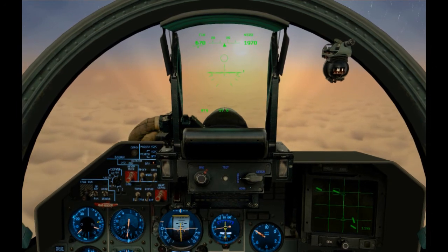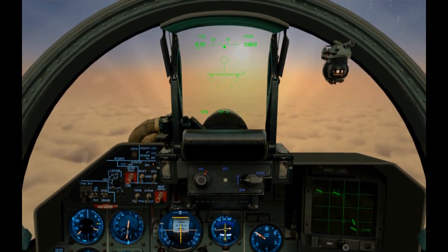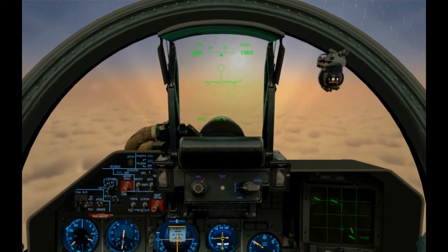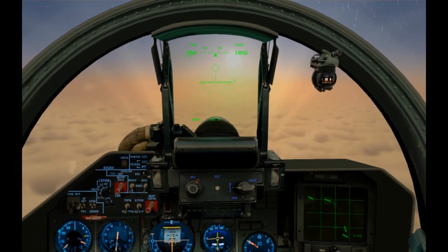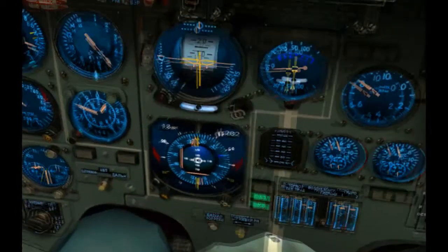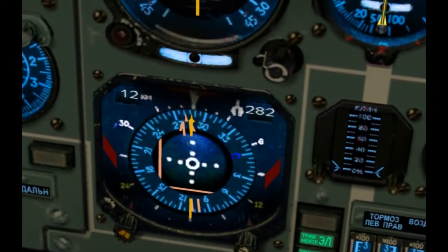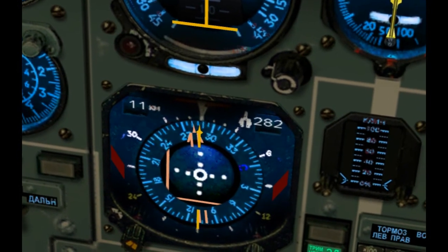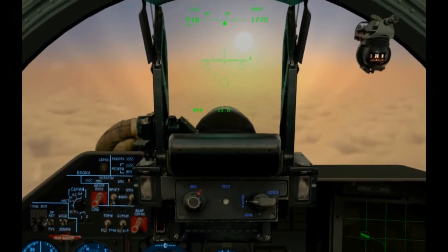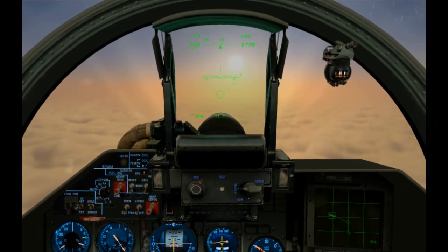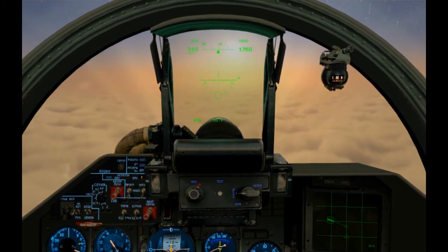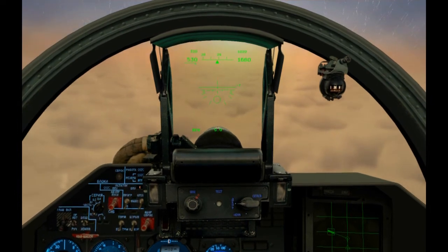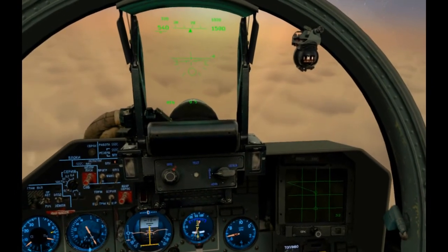Note that the HUD is telling me to fly at a much higher altitude. However, it's going to drop down, and I'm not going to climb just to have to descend later. Also, note that the HSI's white and yellow needles don't line up. This is because we're not on the proper course from waypoint 5 to the initial approach fix. I switched right to return mode after waypoint 4, so we wouldn't have to go all the way to waypoint 5. 10 kilometers from the initial approach fix, we're going to start our descent into the clouds to 1,000 meters.